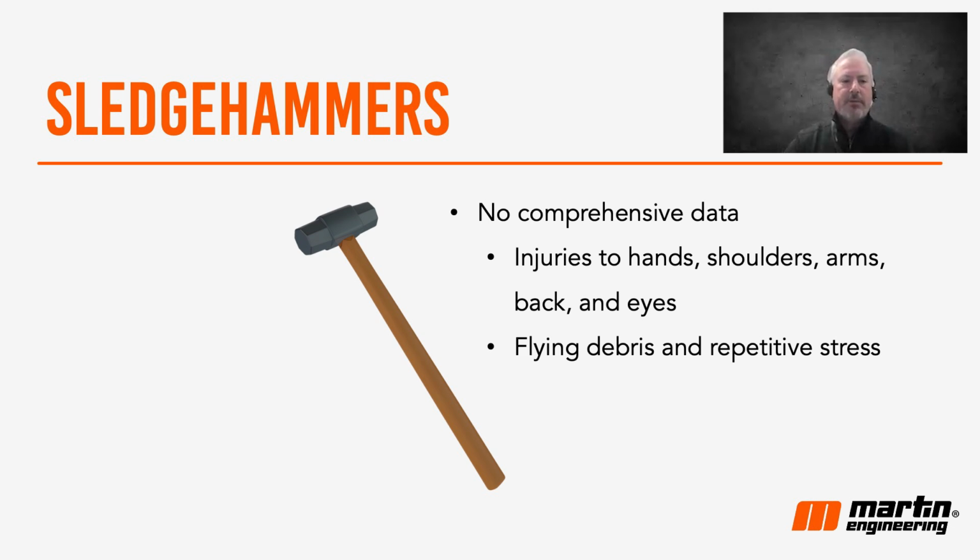Regarding sledgehammers, there's no data available out there right now on the specific number of injuries that are caused from dealing with those, but it's reasonable to believe that there is a significant number. I was in a plant last year, a coal-fired power plant, where they had two shoulder injuries recently due to guys having to swing sledgehammers. And we found that by placing a properly sized and applied vibrator to replace that hammer, they eliminated the need for the operator and thus reduced the risk of injury.